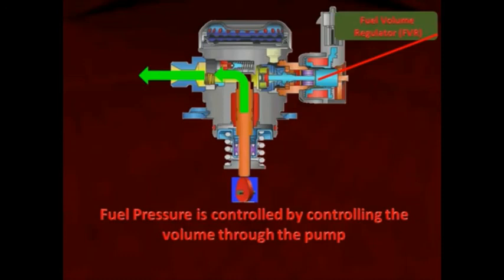It's not a wide range like PFI. What controls the injector fuel flow is the fact that the computer is controlling a solenoid out on the high pressure pump, and it controls it by how much fuel it allows into the high pressure pump.